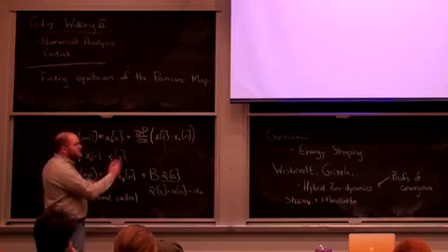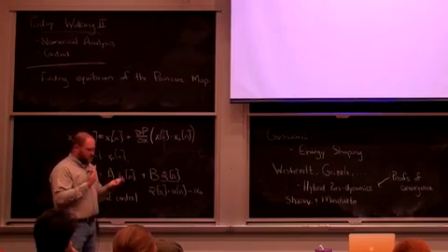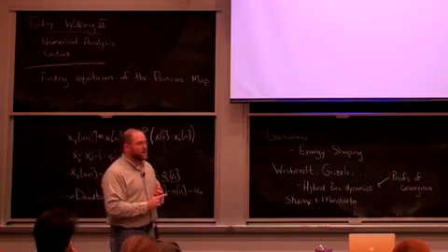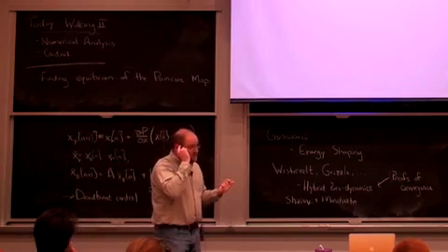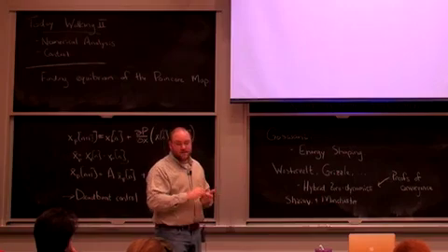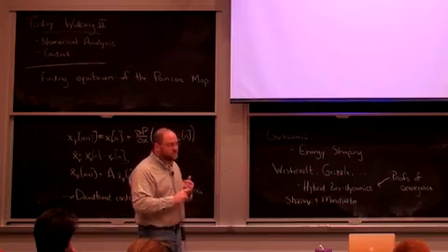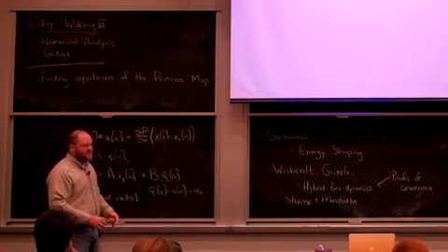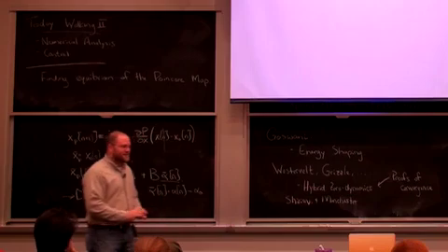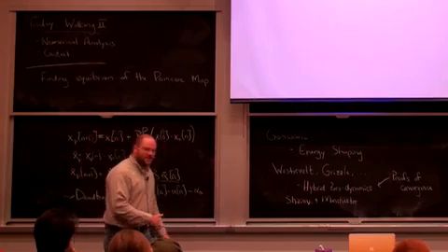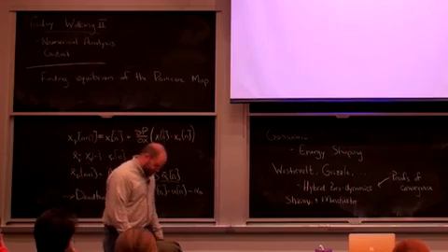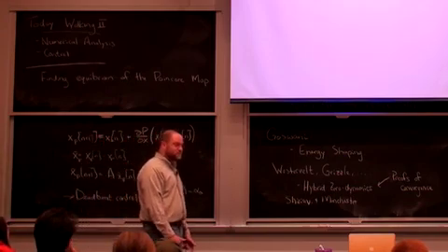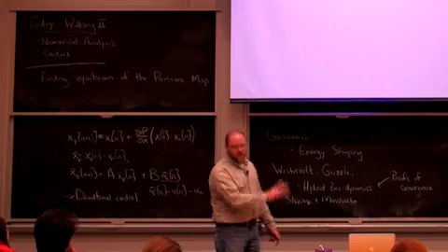That's relatively unappealing compared to these, I think, because it uses a ton of energy. I told you in the first lecture, it uses 20 times as much energy as a human when it walks. People have used these type of methods to make a robot that uses the same kind of energy economy as a human. Right? And it's just walking with its foot flat on the ground. It doesn't work on rough terrain. It's not walking as fast as we are. All the energetics of heel strike, you have to do all that with active control because you can't sort of reduce your collision if you're going to land with a flat foot. So this is the better way to do things.